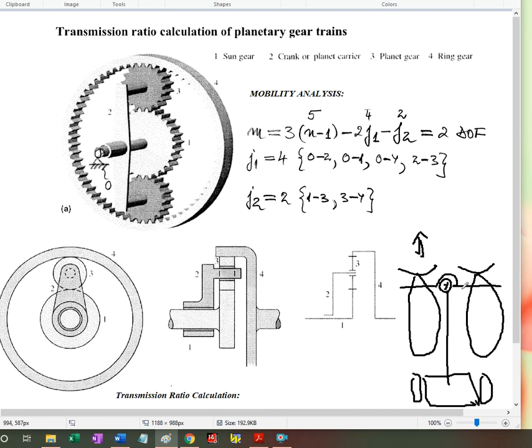There's also possibly, if you have a stronger ox than the other one, usually this would be the stronger ox, you'd make this ox's point where the back of the head is engaging this, I don't know how it's called, shorter. So for a stronger ox, you make this shorter, and for the weaker ox, you make this longer, a lever effect. But in any case, I have two inputs, and this is a 2 degree of freedom system. 1 degree of freedom is moving forward, the other degree of freedom is the pivoting.